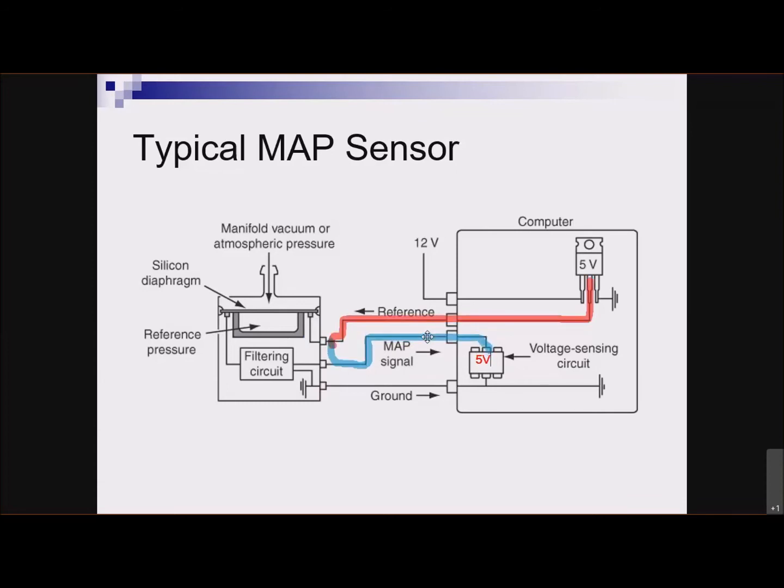You've connected them together. What does that tell me? That tells me a lot. It tells me, one, that this wire is not broken, right? And it tells me this wire is not broken. It also tells me that the computer is able to see that voltage. I'm feeding it in, the computer can see it.